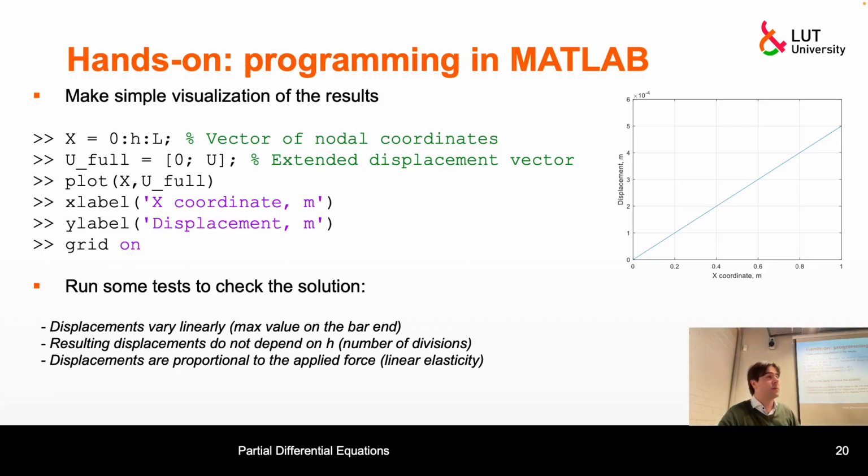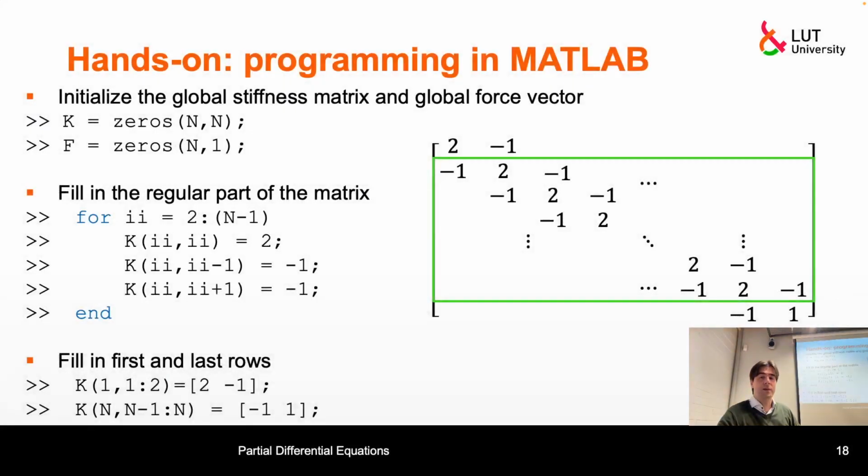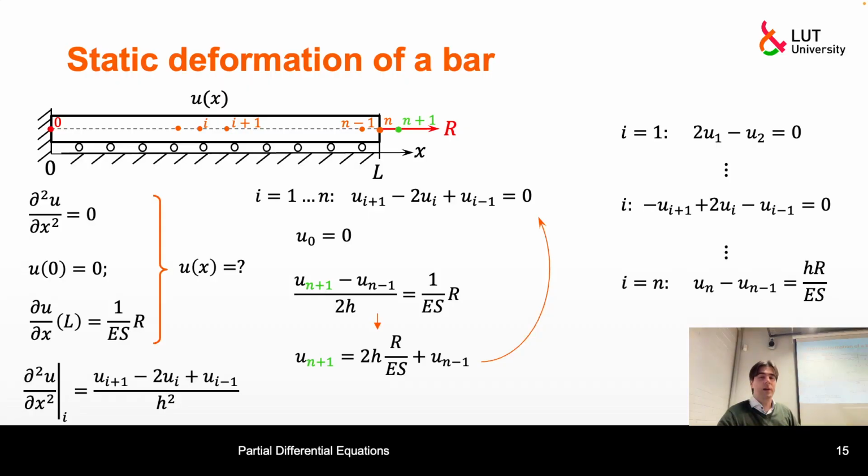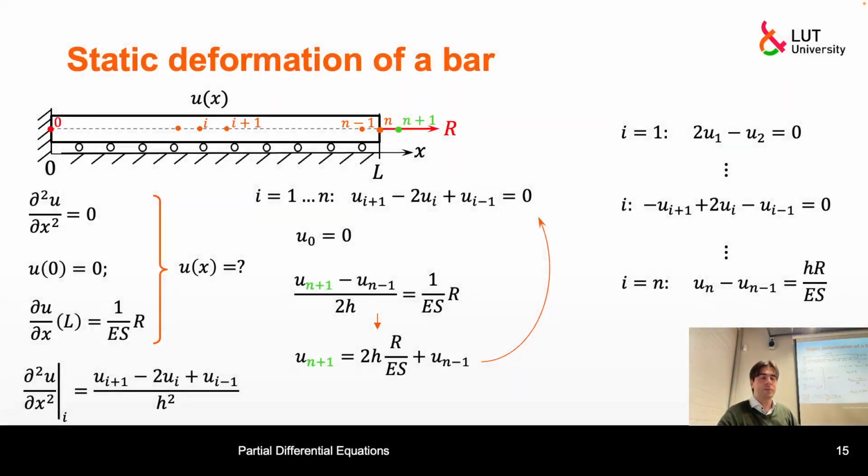And also, please check that displacements are proportional to the force. That's what you would expect from the linear nature of the problem. We are using linear elasticity, and that must result in displacements being proportional to the applied force.